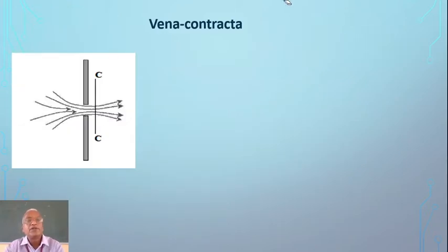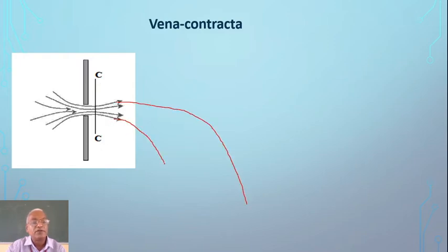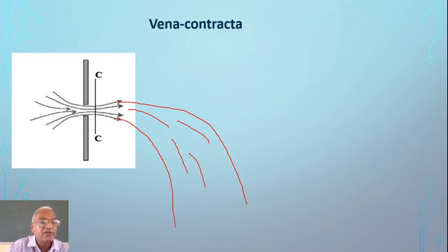Okay, now what is vena contracta? When the jet comes out, I have told you it decreases in its diameter, comes to a minimum, and then slightly diverges, and the jet goes that way, right? So all this will be water which will be coming out. Now the jet will not be of the same size as the opening; it decreases in its size and reaches a minimum size.